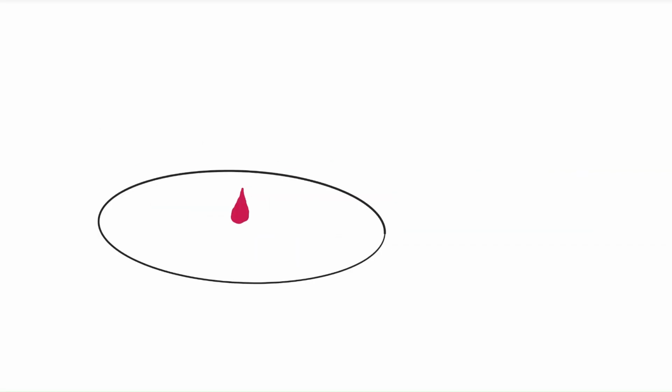Let's go back to our wafer. There's a set of procedures within semiconductor manufacturing called photolithography. Part of these processes involve dispensing photoresist onto a wafer, which needs to spread out, meaning that the surface of the wafer is hydrophilic to photoresist. Consequently, if a drop of water is put on the wafer, it should act in the opposite way, meaning in a hydrophobic manner. The water will bead up instead of spread out. This is a trend that is commonly used to test the surface of a wafer.